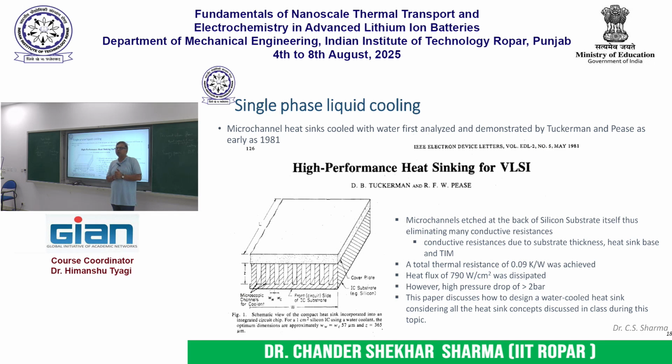So now at those small length scales, as the fluid flow gets miniaturized, turbulence becomes unavailable to us, right. So we are stuck with laminar flow, okay. Now I can generate turbulence at small length scales also, but that would require immense pumping power, which is not feasible in terms of practical usage, okay.